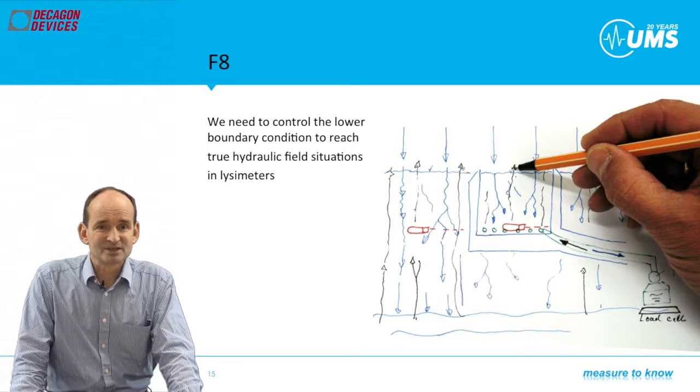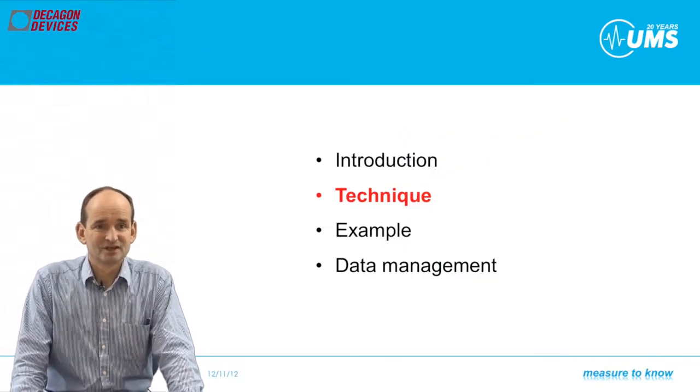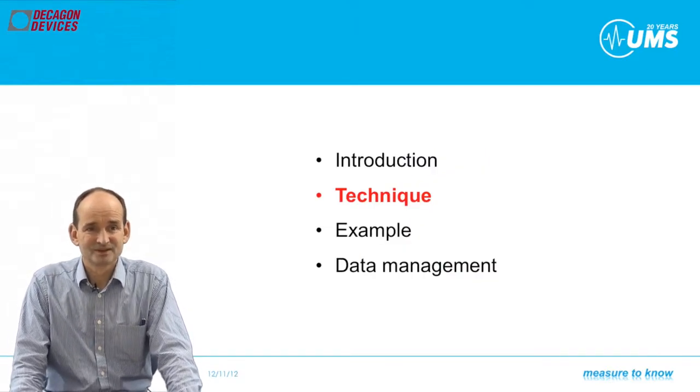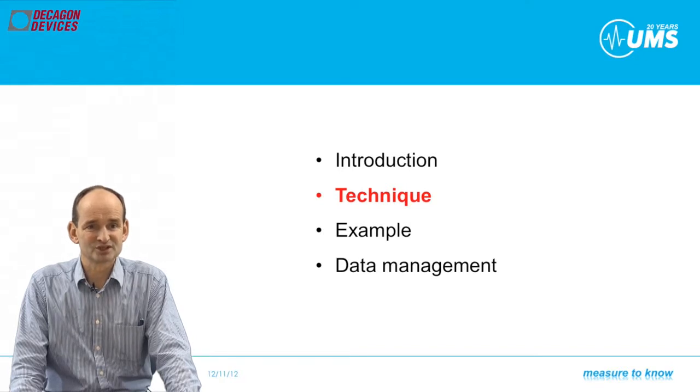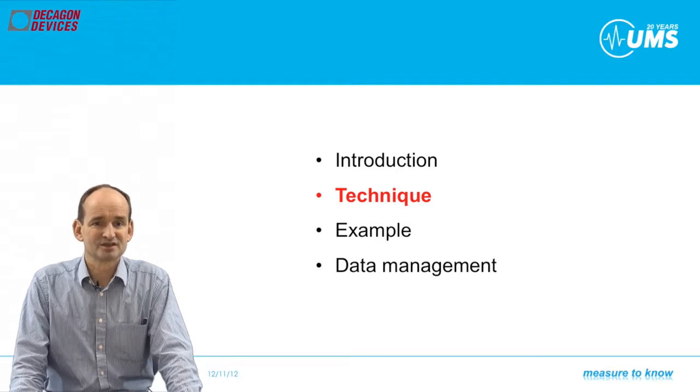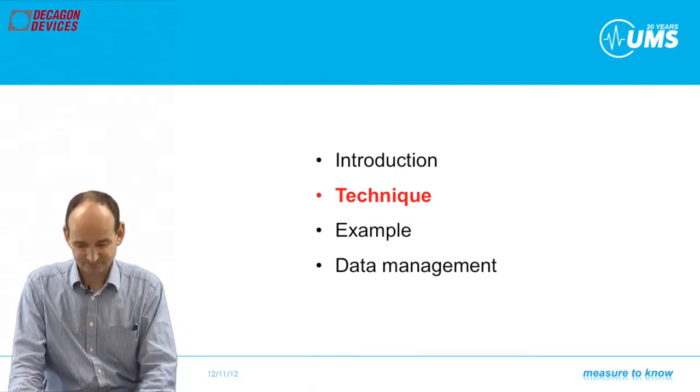The technical requirements in general: high reliability, low maintenance effort, long-term life expectancy for long-term monitoring, waterproof due to field conditions, temperature-proof due to field conditions, easy to use and maintain, and finally, all measurement techniques shall not influence the situation to be measured.